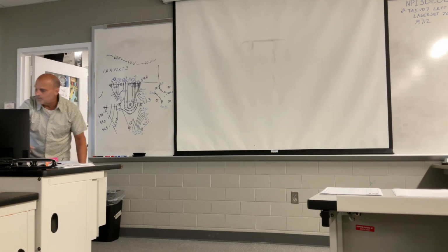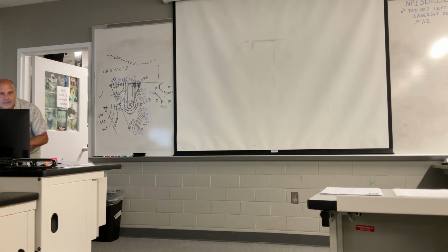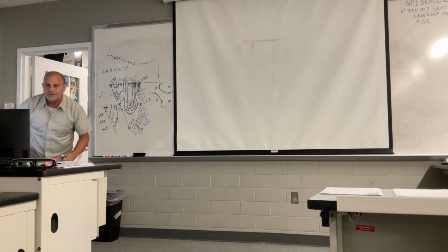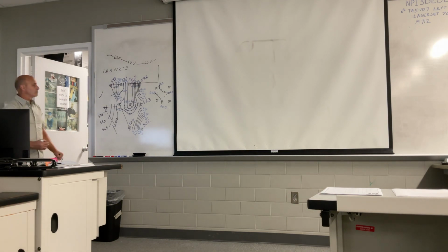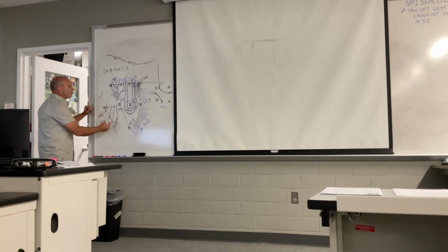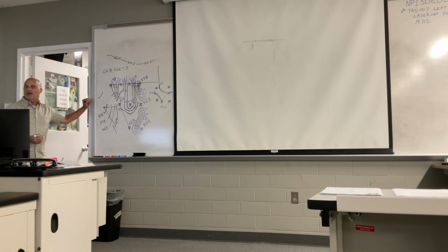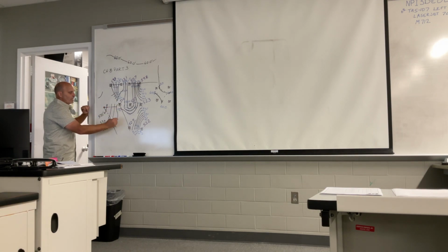Yep, the spline fit command, not the spline CV. Spline fit. So after you get through, something else I recommend, don't just pick a point here and a point there to make that spline. On something short like this, not a problem. But once you get out into that drawing, pick you a couple of extra points in between those.